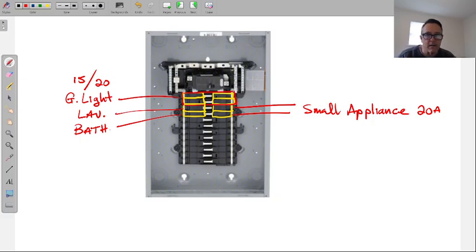There could be 1 outlet in that bathroom. You can have a nice big giant bathroom with 10 outlets in there. Again, don't put that many on a breaker, but I'm just making a point. It's the breaker we're talking about now, not the amount of outlets we're putting out there. If I said we put 12 outlets on a breaker, yeah, do it. You'll get a call from the homeowner at some point: hey, this breaker won't stop tripping.